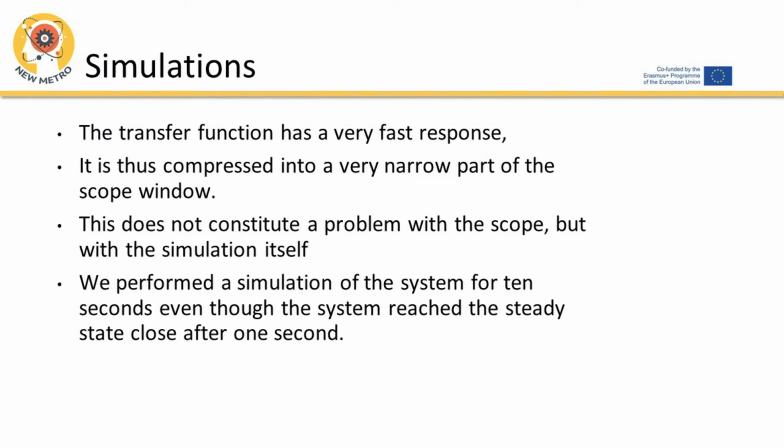The transfer function has a very fast response. It is thus compressed into a very narrow part of the scope window. This does not constitute a problem with the scope, but with the simulation itself. We performed a simulation of the system for 10 seconds even though the system reached the steady state close after 1 second.